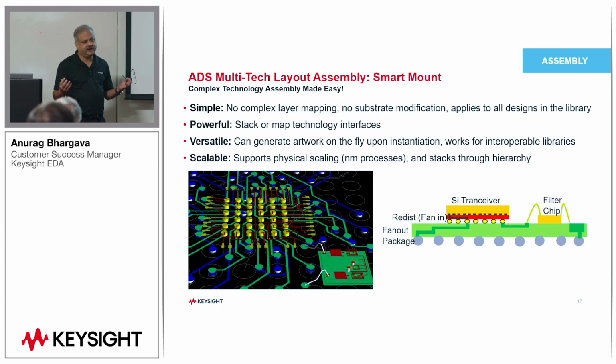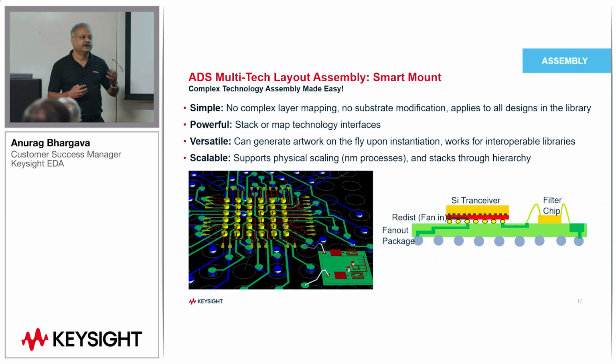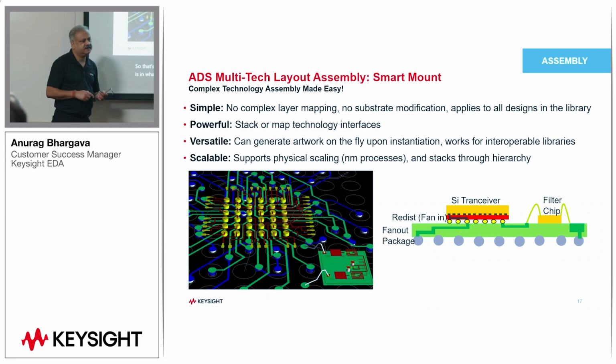But when you're bringing all these form factors together, let's say your IC is in Virtuoso, doing your silicon process design using maybe GlobalFoundries or TSMC kind of process, there are a few ICs being done with GaAs and GaN technology, and something with LTCC. How are you going to assemble all these? Because everything has its own technology stack and its own form factor.